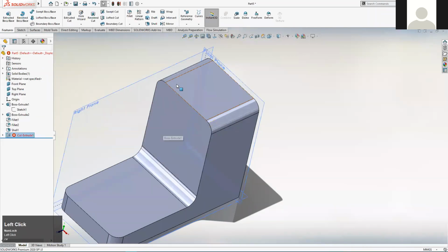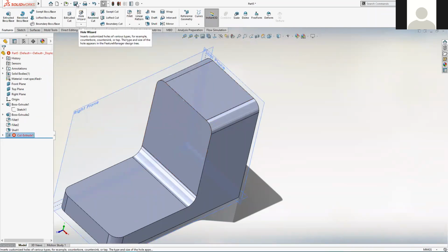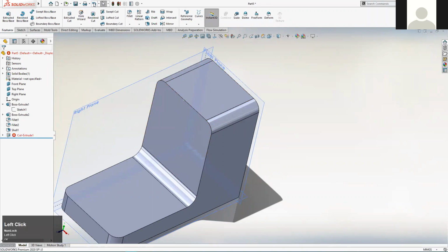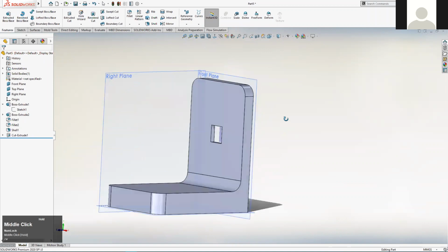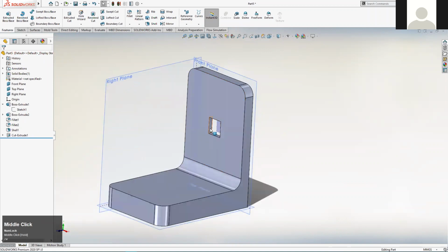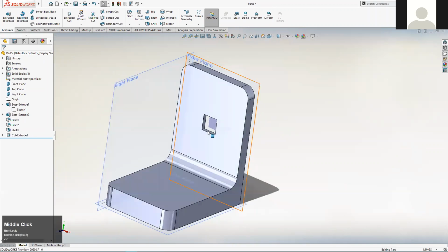But in some cases, you will want to give a cut a depth. I can think of instances whereby I've drilled holes into a block, thinking I'm going to thread these holes, I'm going to tap them and put a thread into them, and I've not wanted to pass all the way through the block. I wanted to stop. So then you would give it an actual depth figure. So yeah, just a little bit of thought about how the design might change in the future, and is this the most robust method to model this feature.